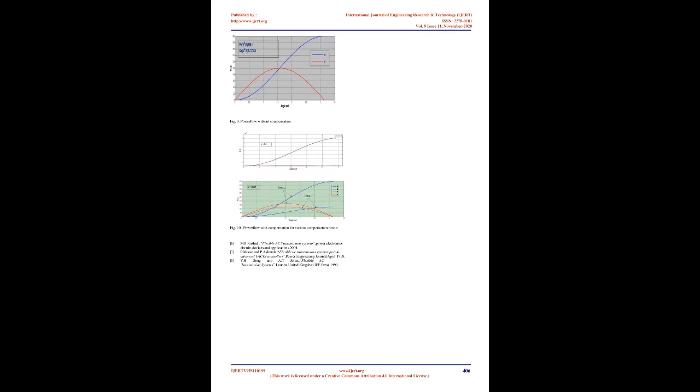As a conclusion from our simulation model, it is observed that the line current in the compensated line increased by about 50%, thus relieving the adjacent line current by about 24%. From a power system point of view, the compensated system as a whole can now handle more power without overloading individual lines. From the simulation it is clear that using TSSC partially offsets the inductive reactance and improves line loading characteristics, thereby enabling power transfer more efficiently.